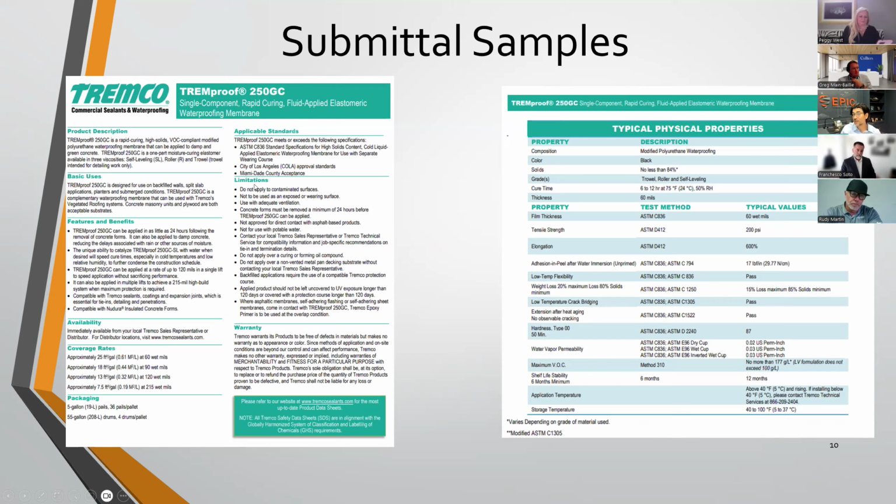So those limitations are going to be critical to understand whether or not it can be utilized in a certain scenario. And if there's any gray area, again, the reviewer is intended to put in whatever commentary they may have and make sure it's part of the record. And also on the back end, you're going to see what tests it meets, what thicknesses, any of the ASTM tests, the American Standards of Testing Materials, to show its performance. So how much can this thing stretch if it's supposed to be a stretchy material, for example. And what is its ponding, like how will it perform under submerged conditions, is another important scenario to consider in the beginning of the design phase, but also confirming in the submittal stage.